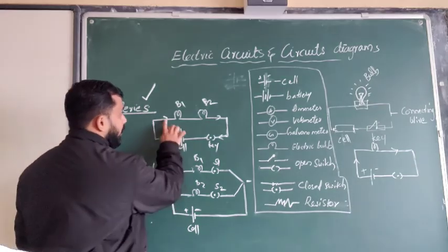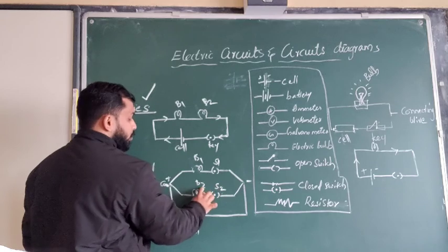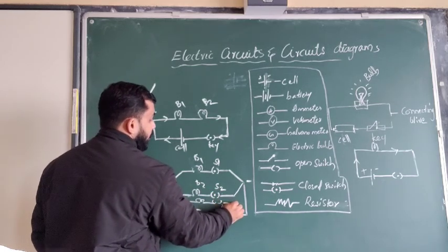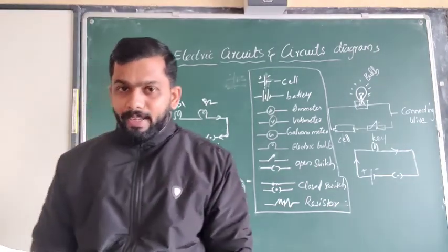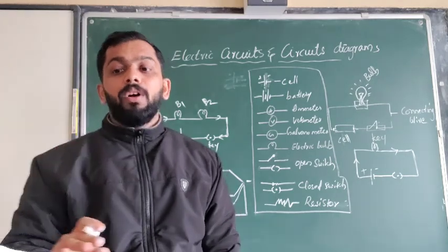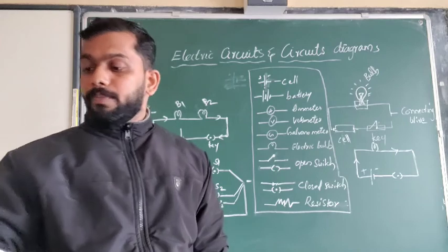Okay, and we know that for the parallel connection we need a greater amount of wire. Here we need only this much wire. Here one is given to bulb 1, one is given to bulb 2, and if there is one more, then bulb 3 gets a separate switch. So this is going to increase the cost of wiring, but this is the best method for wiring.